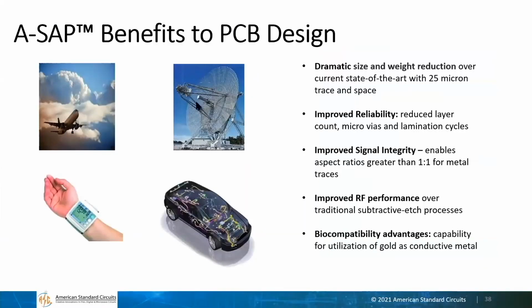So some of the design benefits first. Of course, one of the principal things is to shrink the size and weight. And that's really important because if you look at any modern electronics, it's really not the silicon that's occupying very much size or weight. It's all in the plastic and metal that connects the silicon together, the packaging, and probably more important, the printed circuit board.